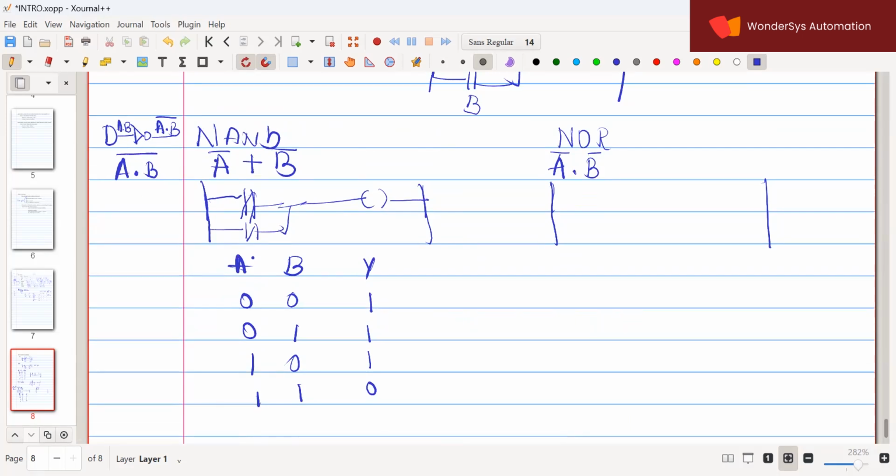Now, for this operation, you cannot realize it in ladder logic, because A, B is acting like one term now because of this complement. Now, based on De Morgan's principle, whenever there is a multiplication and a complete bar, I can convert it into individual NOT operations with the addition mark.